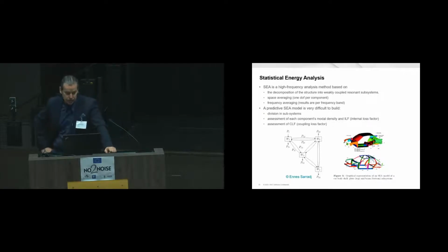Statistical energy analysis. It's a high frequency analysis method based on production of a reduced model based on energy exchange between subparts of your model. You have to decompose your structure into weakly coupled subsystems, and then you have some analytical prediction of the way energy is stored, dissipated, and exchanged between those subsystems. The problem is that it's not easy to define a substructuring that is weakly coupled and for which each subsystem can be reasonably well described by some analytical model based on infinite curved or flat plates or beams or stuff like that. So it's not so easy because of those two issues.